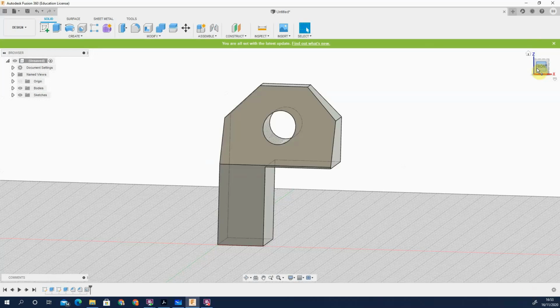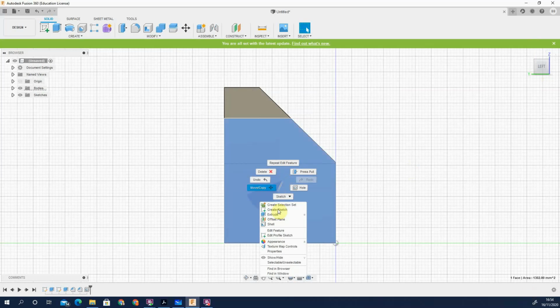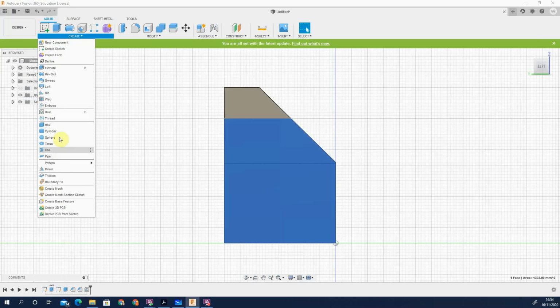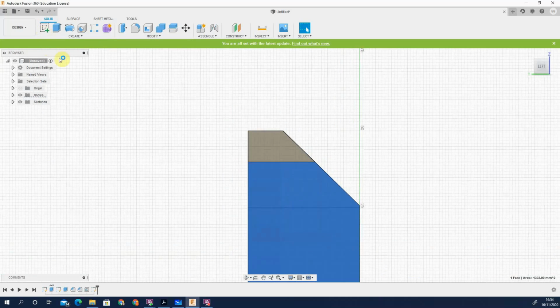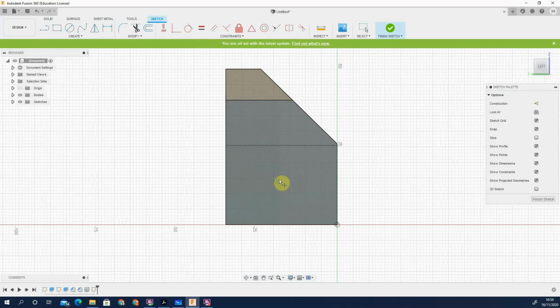Now, when we draw it on the other side, we can draw it on our left-hand feature. So to make it nice and easy, I'm actually going to draw a sketch of it first. I'm going to draw a couple of points where I can. So I'm going to come down and choose point. Once I've created my sketch, come down, find the point function, place one point. Now I'm going to offset that one point, so obviously from the left it's 17.5.